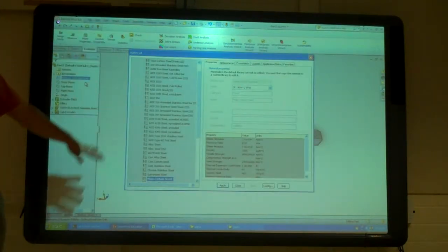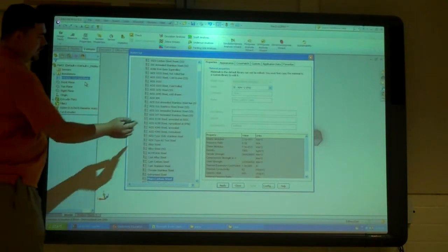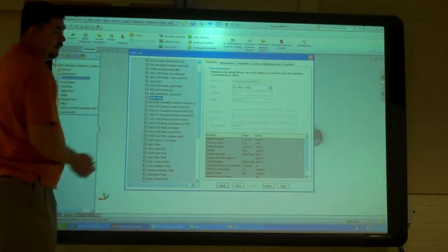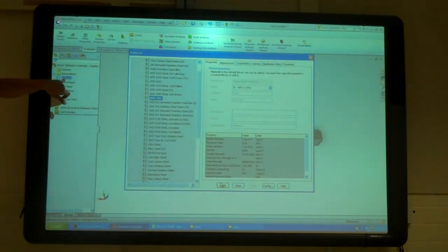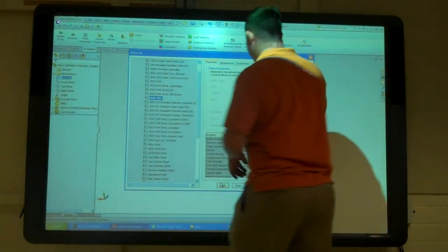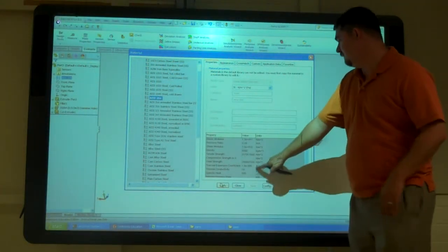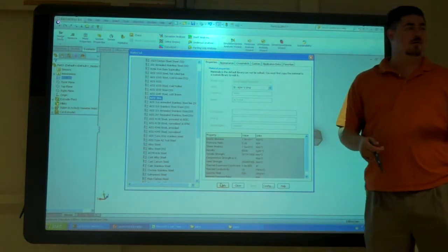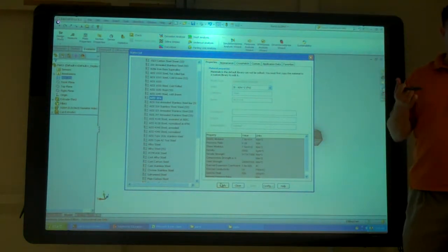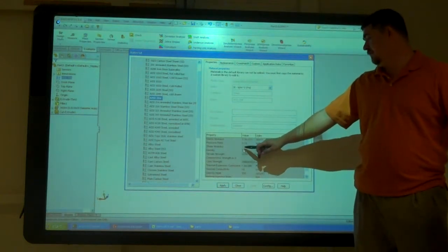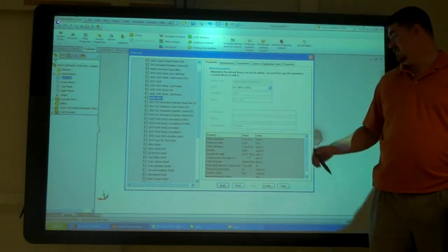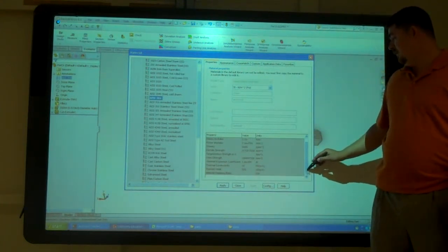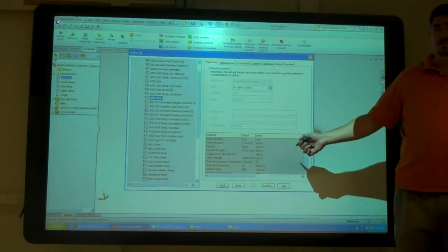This is where you see the full list of materials also. So you could decide that I want it 304 and hit apply, and now I'll just apply that to the part. And you can see that it has properties. Not only do I have the weight, the density, but now I have shear strength, tensile strength, yield, elasticity, all that stuff. And why do you think I bought all that stuff?